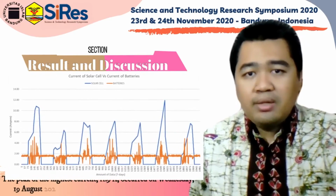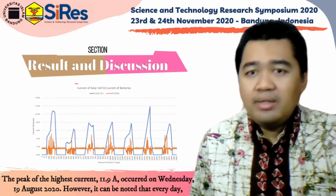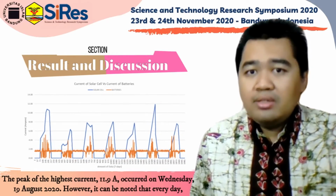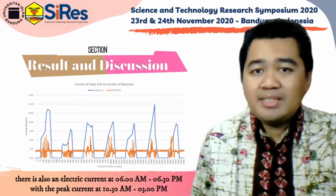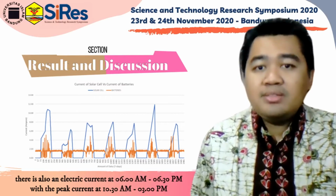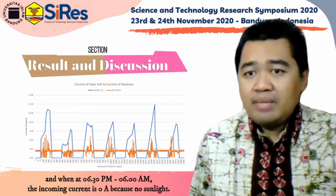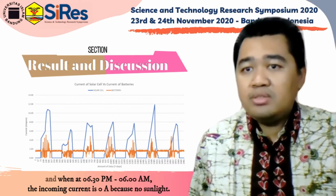The peak of the highest current, 11.9 ampere, occurred on Wednesday, 19 August 2020. However, it can be noted that every day there is also an electric current from 6 a.m. to 6:30 p.m., with the peak current at 10:30 a.m. to 3 p.m. And when at 6:30 p.m. to 6 a.m., the incoming current is 0 ampere because there is no sunlight.